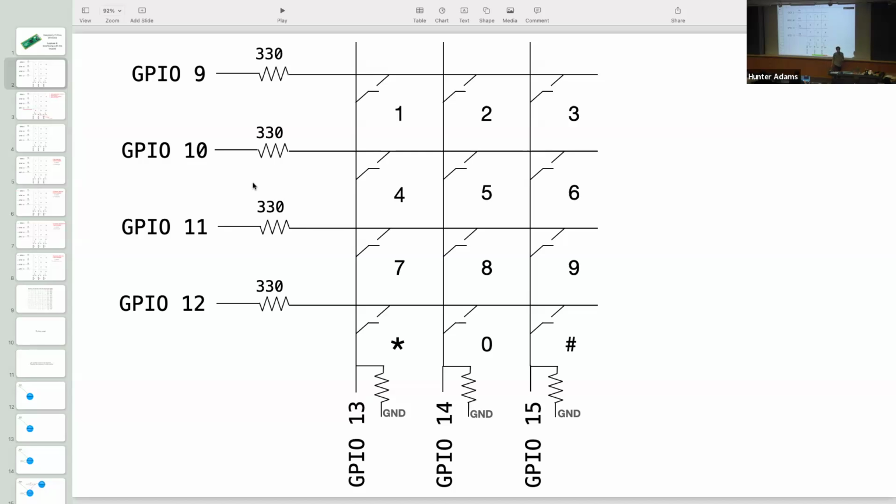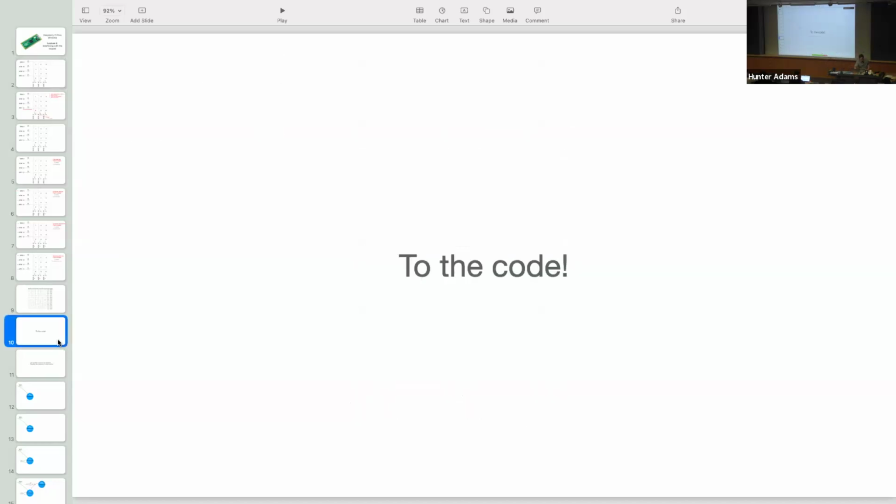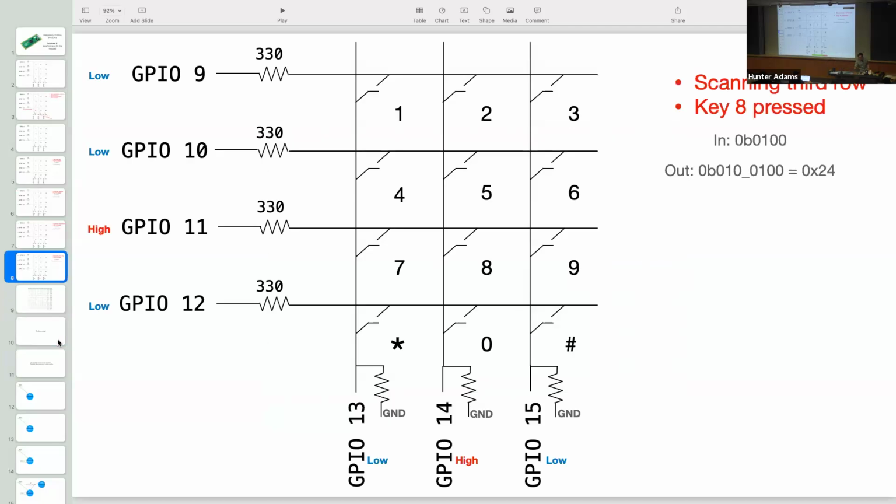And so what we need to implement is a debouncer. In our case, it will be a software solution to this problem, though as some of you have pointed out, you could certainly solve this problem in hardware as well. And if you would prefer to do that, you're very welcome to do that. So what we are going to do is debounce this thing so that we only report a button as having been pushed when we measure it in a stable state. The bouncing has stopped.